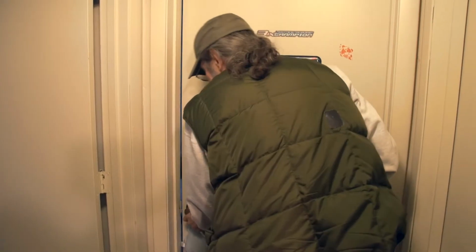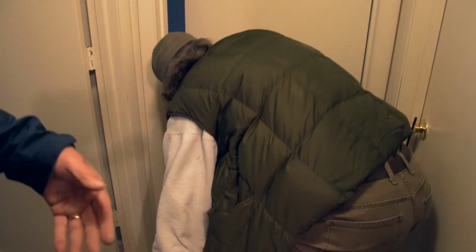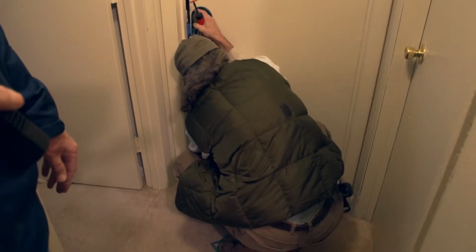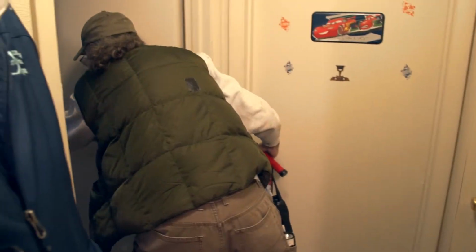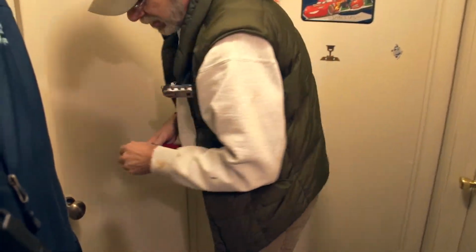Once all of these items are on, we can begin going around the house and checking our pressures by opening and closing the doors and see whether or not opening and closing those doors makes our pressure in our CAS worse or better. In our case, worse is always going to be a more negative pressure, and an improvement in our CAS is going to be a positive pressure.